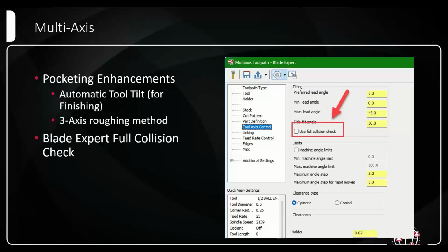While they were weighing whether or not to switch over to a longer toolpath calculation time but a safer calculation method when it came to collision checking, they decided to go ahead and give you the power to decide: do you want fast generation with the potential that there might be a little bit of a clipping here and there, which you would hopefully see in the verify and correct with other parameters, or do you want it to take a little bit longer to calculate but be a little more careful when it comes to collision checking, essentially?